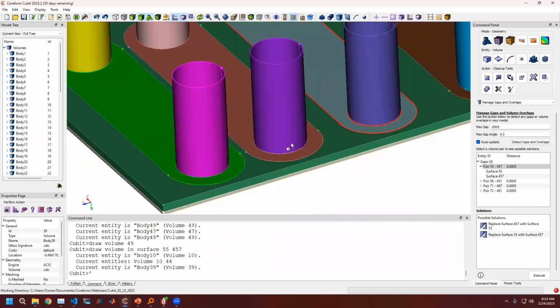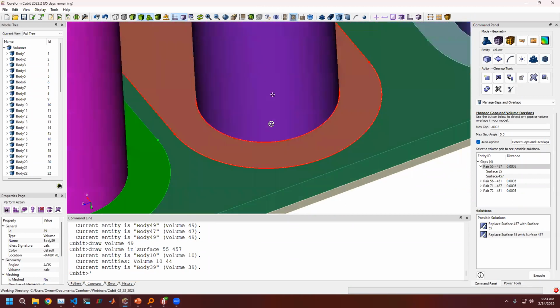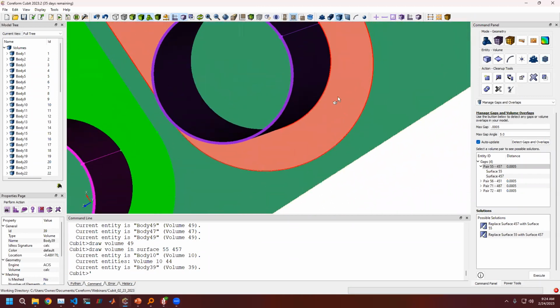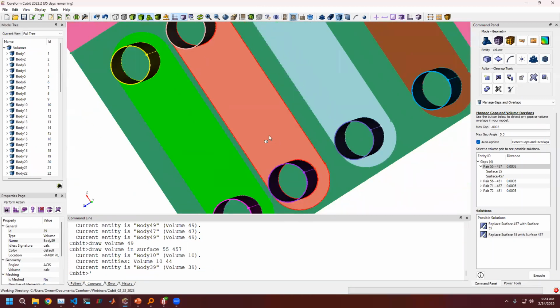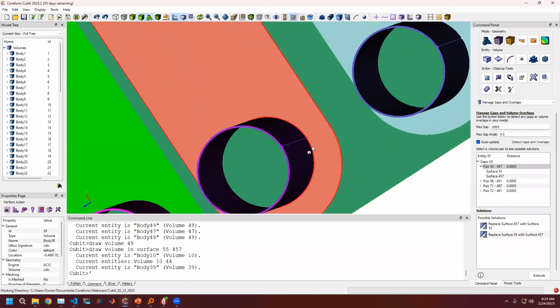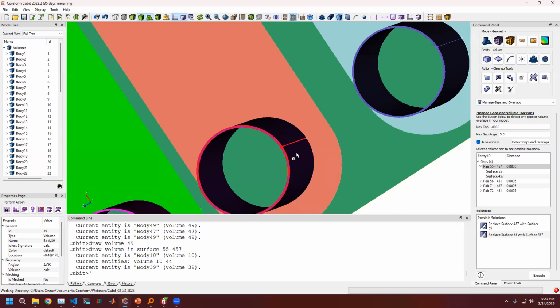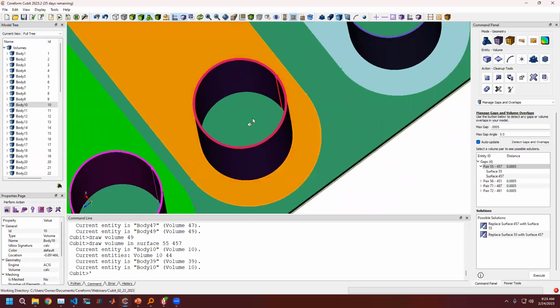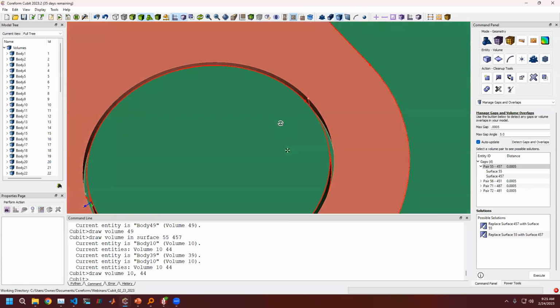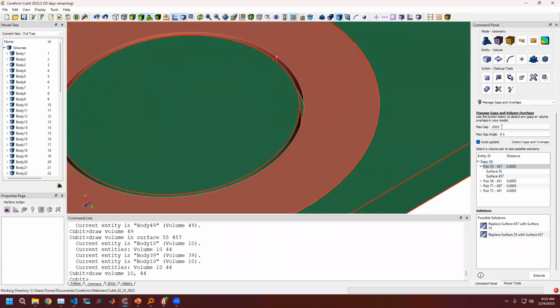via up here that actually fills this gap that's between the layer and another, like a bridge here, a copper bridge. So the problem is, if you imagine we've got these little tubes that are covering between these surfaces, those tubes are essentially inside this gap tolerance that we've set, that's pushed off from the absolute tolerance. And again, I'll mention what that absolute tolerance actually is in Cubit. We've set it to 1e-6 for now.